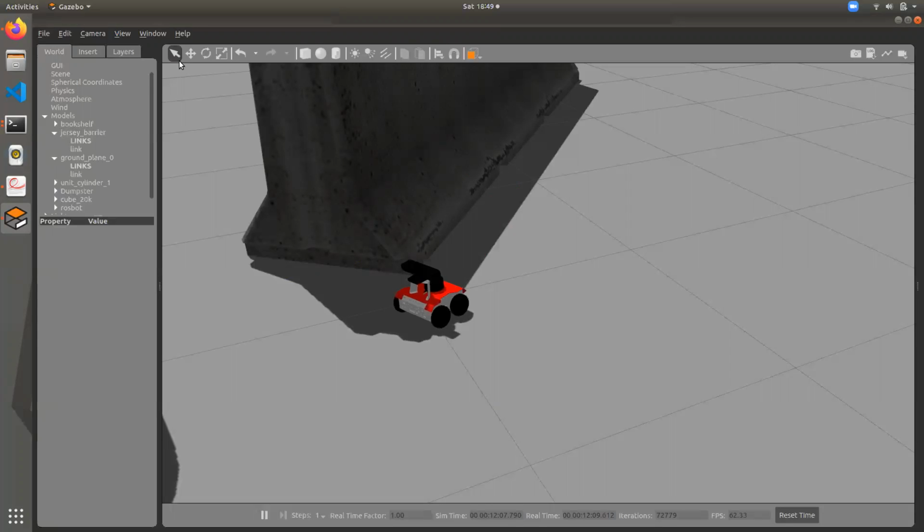But you can do something like this. Earlier, there was a joystick kind of thing. What happens is joystick commands are understood by the ROS node specified for that, and it's sent there. There are some implementations like that. You can create an app, and you can create a server in the cloud, and you can send the movement commands to the server. On the ROS network, you can create a node that listens to the server.